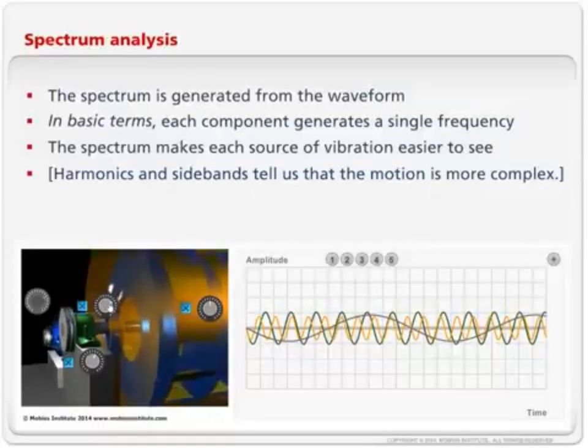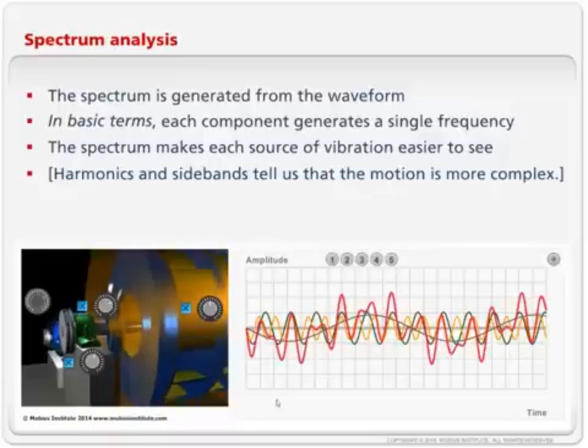Unfortunately, it's more complicated than this. Not only do bearings create a very different vibration pattern for that, but, in simple terms, they do have their unique frequency. But what we measure is the combination of the grey, the green, and the orange vibration, which looks something like that. That more complicated squiggle line there, the time waveform, is the combination of all those motions. And so that's what the vibration analyst gets out of that sensor that's placed on the bearing. And it's like, okay, what can we do with that?